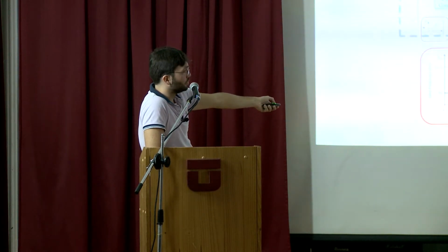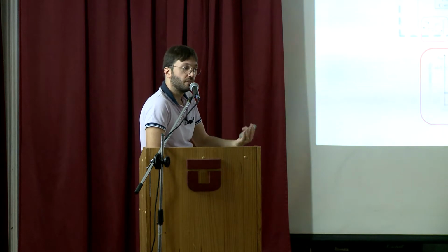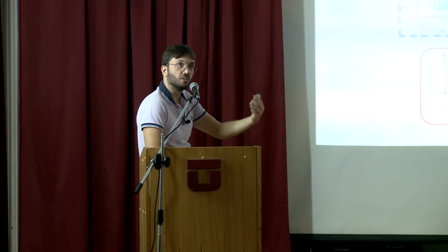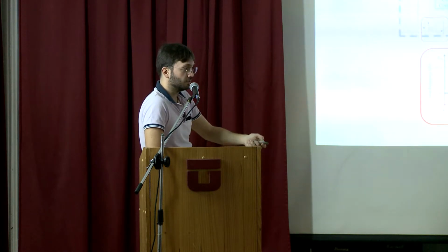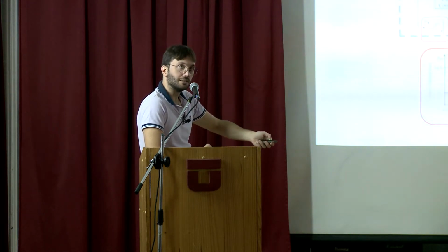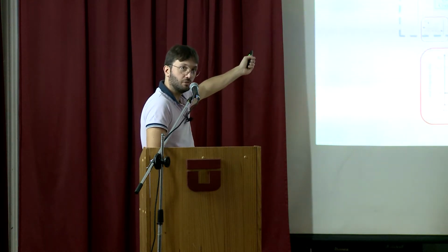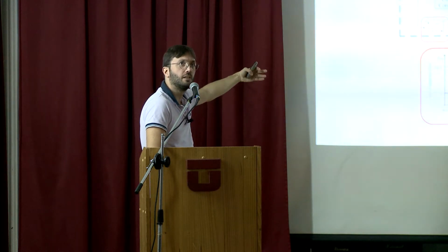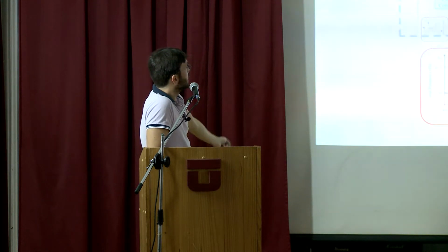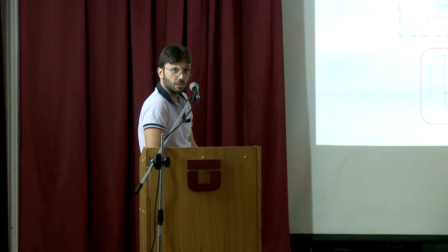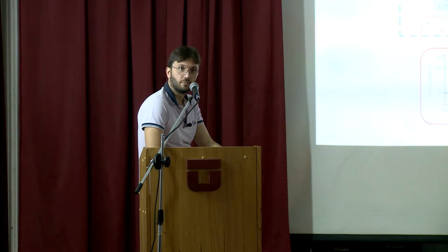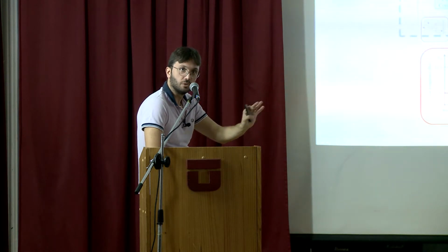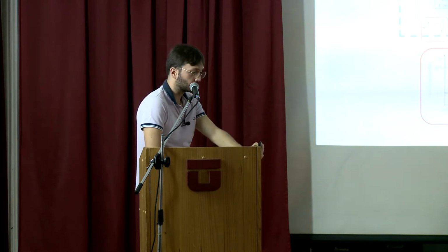So this lookup table is there because if the frequency of the grid is increasing, then I cut the power. Normally the power should go up to the medium voltage, cause the problem, and then I cut the power. With a smart transformer, I do this completely in the low voltage network. I don't cause any problem to the medium voltage network.